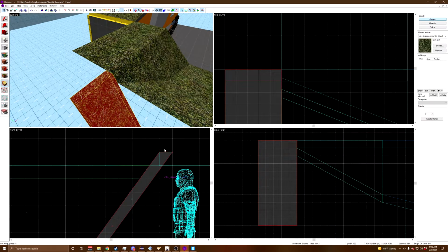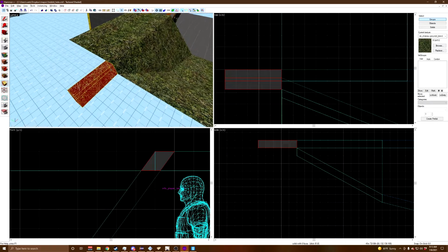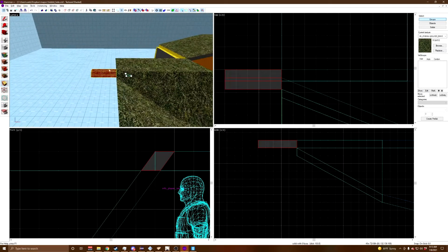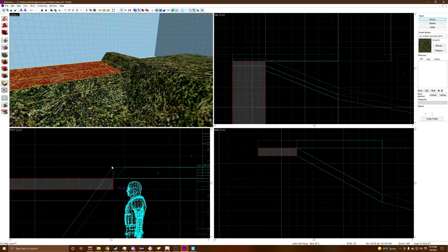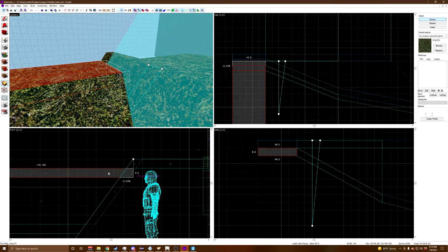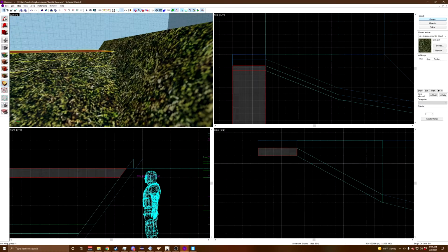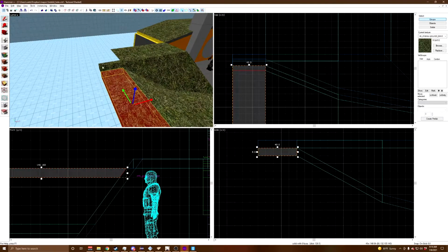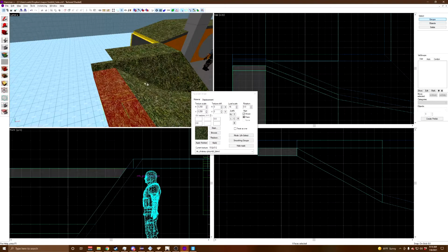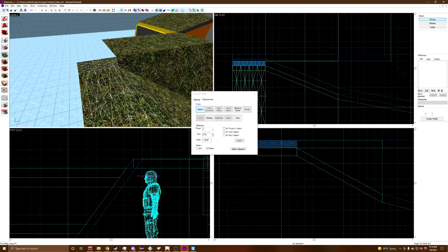Finally, I'm going to use the clipping tool to shave off everything except for the top 8 units of this new brush. Of course, this leaves the bottom vertices off grid, but we have ways to deal with this. Create a flat brush at the top of the ramp and use the clipping tool to cut off the side of the brush so that it matches the slope of the wall it's adjacent to. This, while still being horribly off grid, is still completely sewable with all adjacent displacements. And that's the important thing that we're looking for.